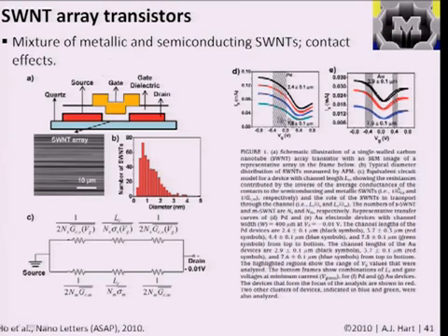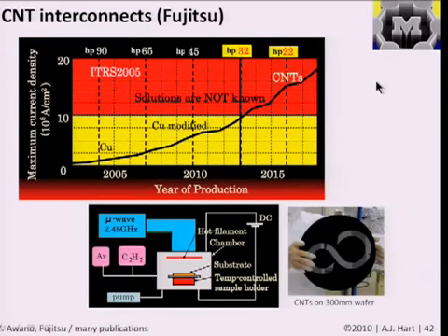But one of the major conclusions of this paper is that because of how the electronic structure of the metal contacts they apply interacts with the electronic structure of the nanotubes, you have effectively much greater transport when you have palladium as your contact metal versus gold as your contact metal. And this issue of what metals are useful for contacting different types of nanostructures is a very important one that we'll learn about later as well.